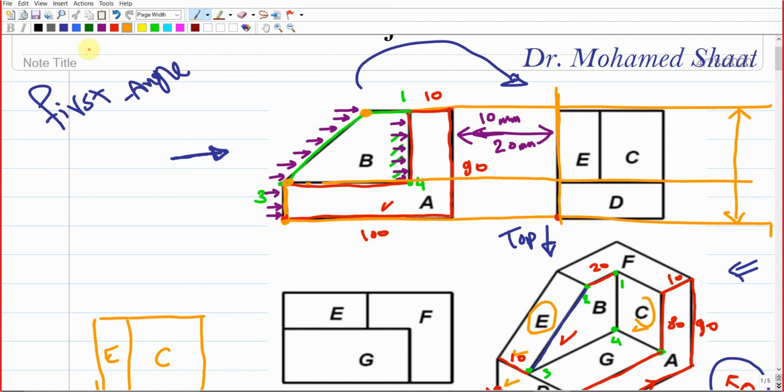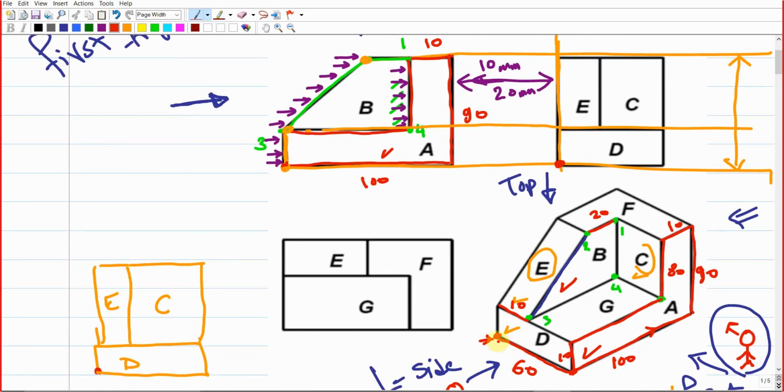Then starting from this point, which should be the lower left corner, I'm gonna draw a line. If you're standing here, moving to the right, I'm gonna move to the right with 60. Then I'm gonna jump up with this height. This height is already 10. And then you're gonna move to the left. And then you're gonna drop down. As you can see, this D should be confined within these two lines. This is the height of surface D, which should typically be the same, because this edge is one of the edges of this surface D. So the drawing is consistent.